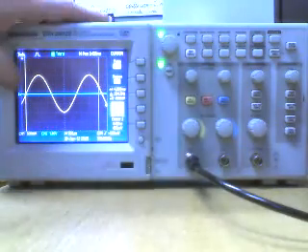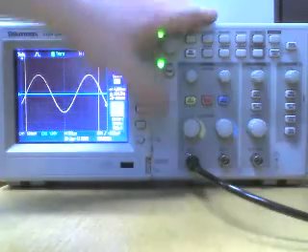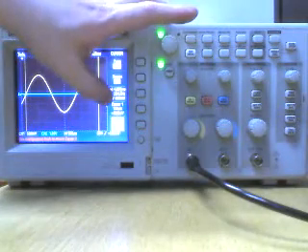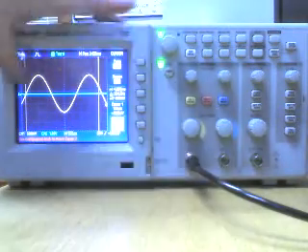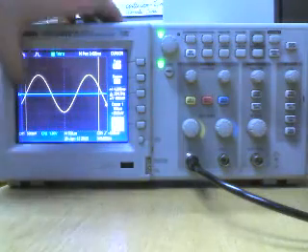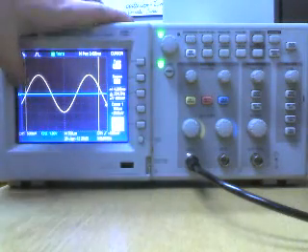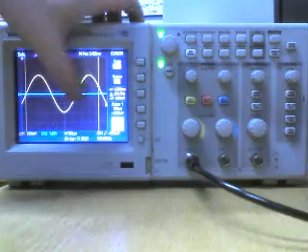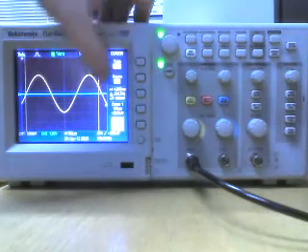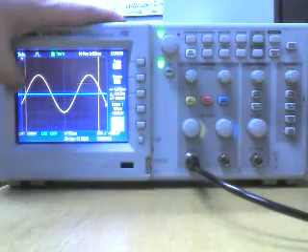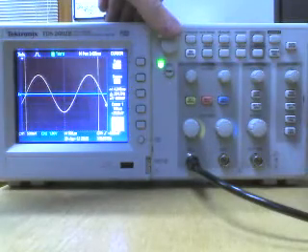Okay, so it's at the 0 crossing point, and then cursor 2. On the screen here, it's 500 microseconds per division. Our first division, where it crosses, is 160 microseconds at minus 20 millivolts. That's very close to 0 where it's crossing.